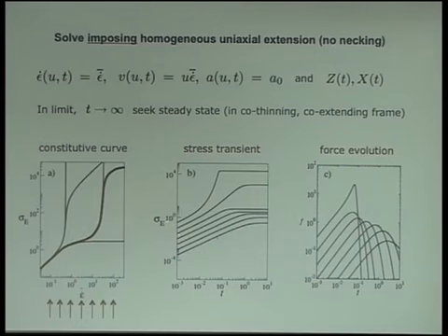It does that for all these low values of the rates, but at a high value of the imposed rate, it does something else. It initially curves upwards. Actually, we have to be careful, this is a log-log scale, but it does the same on linear too. Curves up and then has a point of inflection and then eventually curves down. And that point of inflection is going to be important in what I'm going to say next. So remember that point of inflection. Now the force is a product of a stress times an area. So it initially increases because of the stress and then it decreases because of the exponentially declining area of the filament. So the force does this as a function of time.